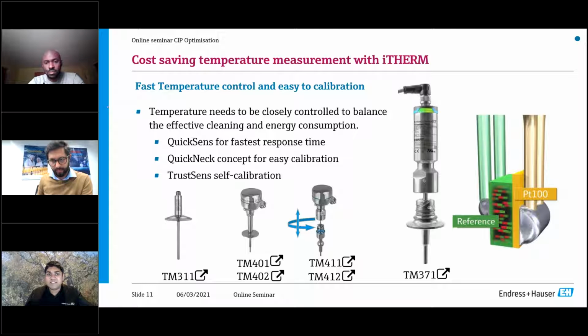at 118 degrees. But you might be saying, Dhiren, you're beating around the bush here, because you just told us that the CIP process only measures between 60 to 90 degrees, and now you're talking about a calibration probe that calibrates itself at 118 degrees. Well, the reason I mention it to you is a traditional temperature calibration can vary between 3 to 5 points that you have to calibrate.